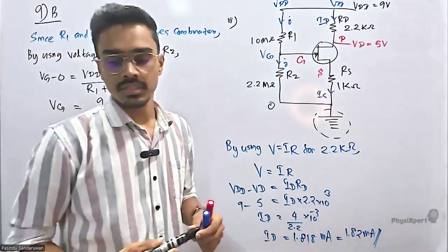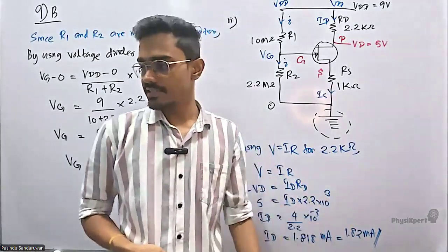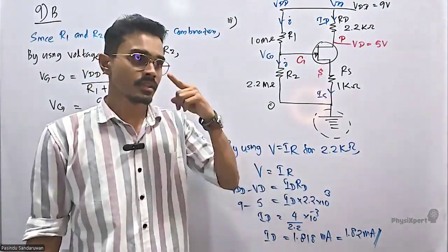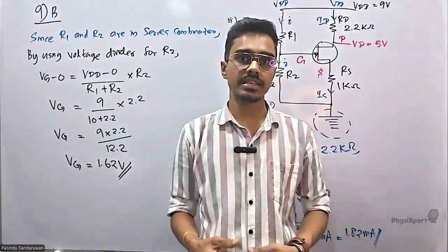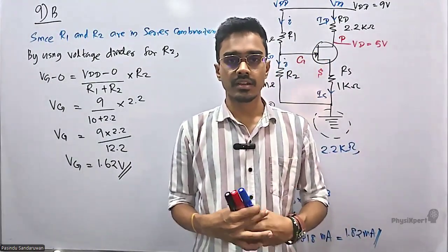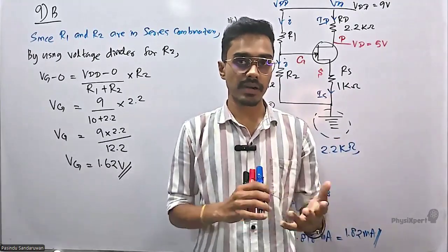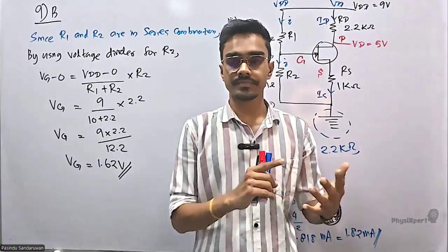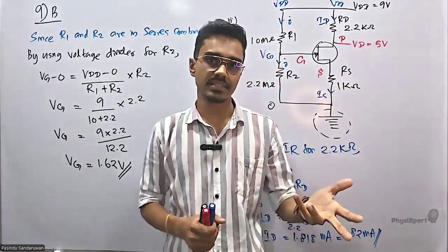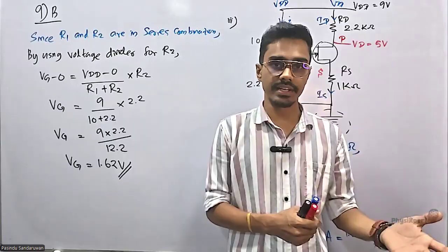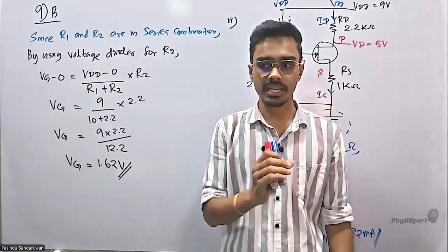Now we need Vs, because to determine VGS we again need Vs. There is another proved equation, VGS equals minus IDRS, for FETs, unipolar transistors. But if the unipolar transistor is in a voltage divider circuit, that cannot be used. For other cases it can be used, except the voltage divider. Keep that in mind.